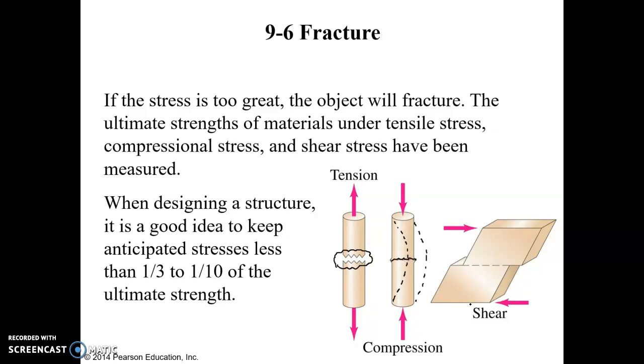And with shearing, again, the forces are running parallel to this plane, or actually this would be the shear plane right here, where the material is actually shearing apart. And it's basically slicing into these two pieces, the bottom part going to the left and the top part going to the right, just like the two blades of a pair of scissors running parallel to each other. So that's a shear failure. Shear failure, it fractures along the plane and splits apart. Tension, it just breaks into two pieces. And with compression, it crushes.